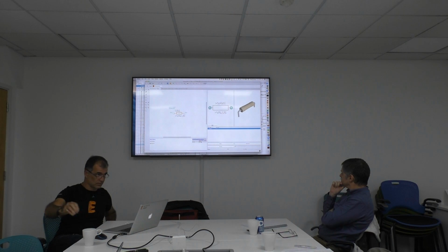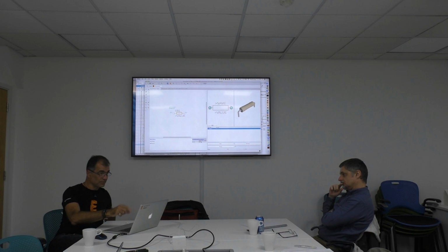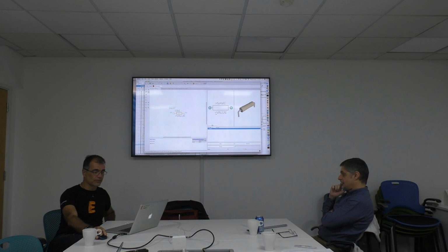Of course I can add attributes. If you would like to see the name and the value of the attribute in the schematic or on the board, then you could set a placeholder text with the name manufacturer. As we do it here with name and value, as a greater sign manufacturer, place it anywhere, and then it would appear also in schematic or board if you want to have this. Okay, that's it. So now we have our device.